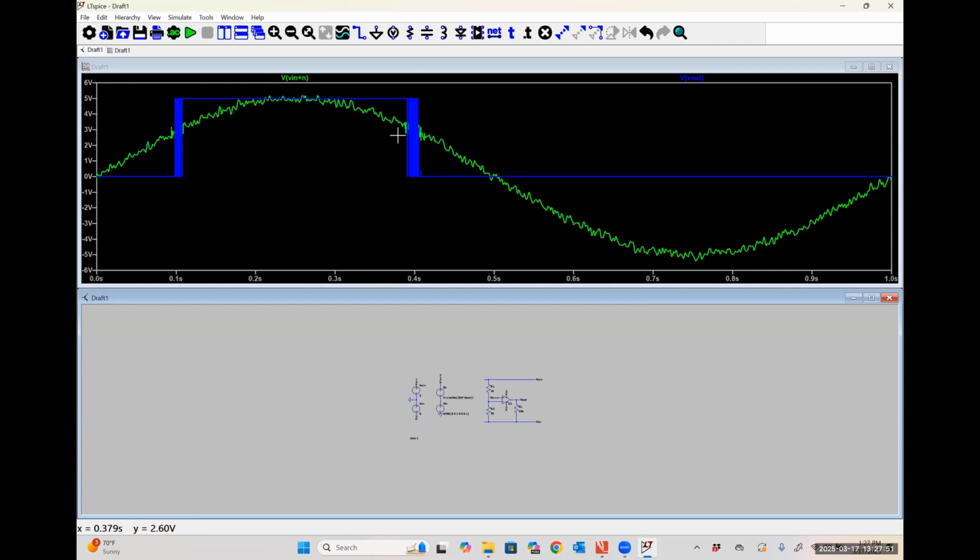So it is. Because my comparator circuits are so sensitive, because we have that open loop gain that is really, really high, anytime my voltage is even slightly over my reference voltage, it's going to swing up to VCC plus. And anytime it's slightly below my reference voltage, it's going to swing down to VCC minus. So if I have a noisy input signal like this, I'm going to see effectively ringing. My output voltage is going to swing between VCC plus and VCC minus until my input signal is consistently either above my reference voltage or below my reference voltage.